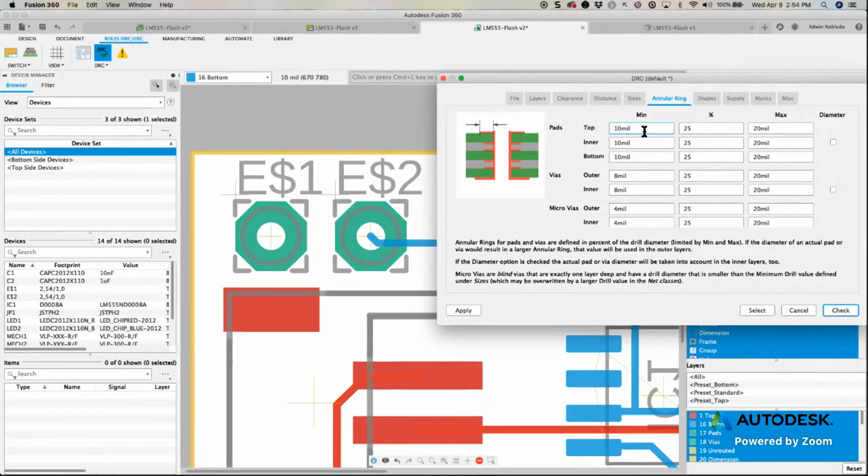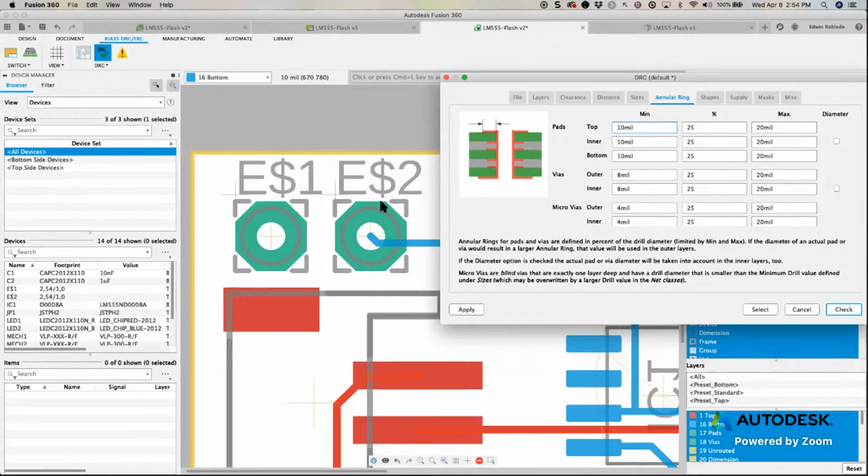Correct. So you broke out there just a minute ago, Jorge, just to let you know. It was just for a few seconds, but it was kind of key. What Jorge was saying at that moment was that when you bring it into the board, you'll notice that your pads are swollen compared to the value that you had set for your pad's diameter in the actual library. What happens is that Fusion 360 will use the value that wins, whatever is larger.